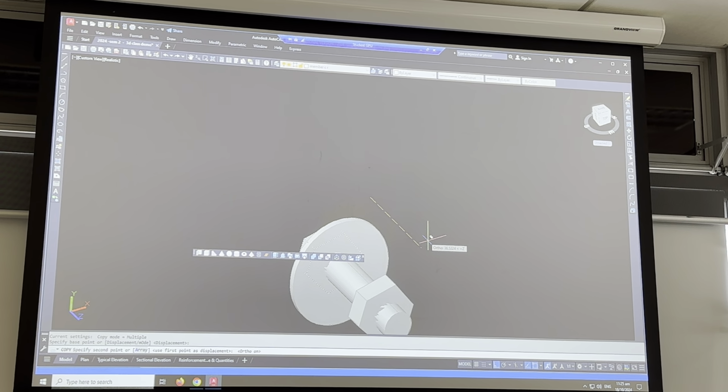This will have to be set to the nearest mill to get it right for all your other calculations, and level. You can't have the nuts on an angle. So you do need really good concrete layers to get that. Whereas this way, you just drill into the concrete afterwards and put your Dynabolt in. It's a lot easier, yeah. And you drill through the holes in the plate, so you don't get it wrong.